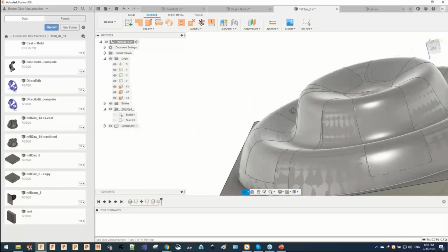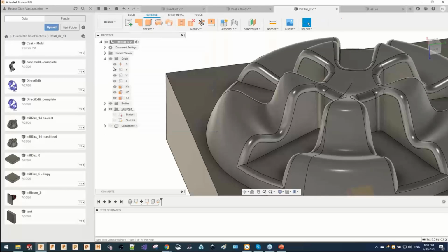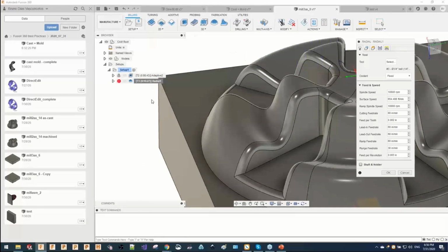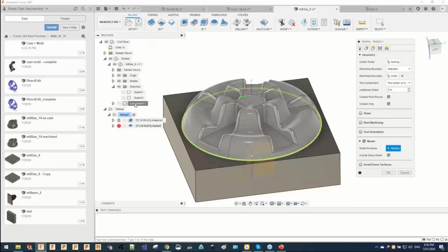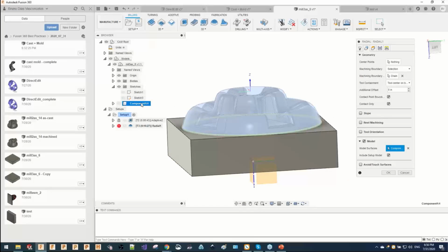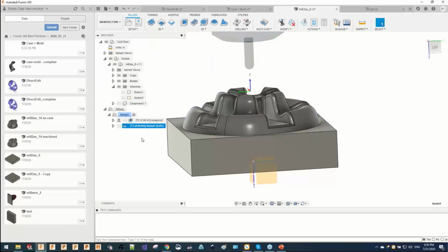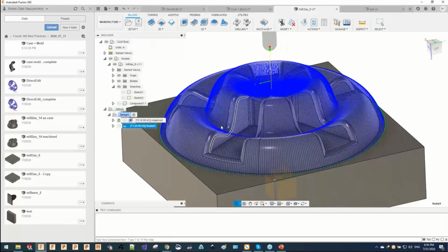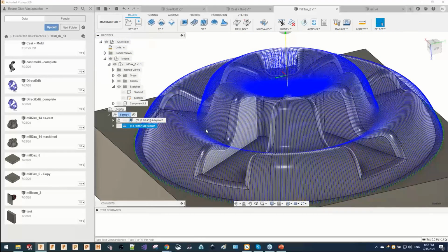So this is what I'm looking to use in my operation. This is the surface that I'm looking for my operation to use. So when you go to Manufacture, right click, Radial, Edit, go to Model. And like I said, all the operations have this, all the 3D. You can come up here and say, hey, use that as part of my model setup. Use that as part of my setup model and do OK. And there you go. So now you're roughing and you're finishing without diving into those areas.